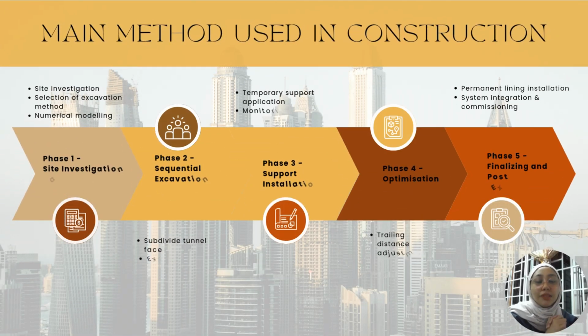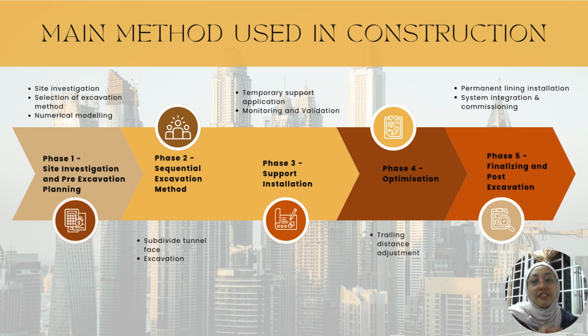So I'm going to explain the method used in construction for this project. This method has 5 phases. Phase 1 is site investigation and pre-excavation. Phase 2 is sequential excavation method. Phase 3 is support installation. Phase 4 is optimization. And the last one is finalizing and post-excavation.